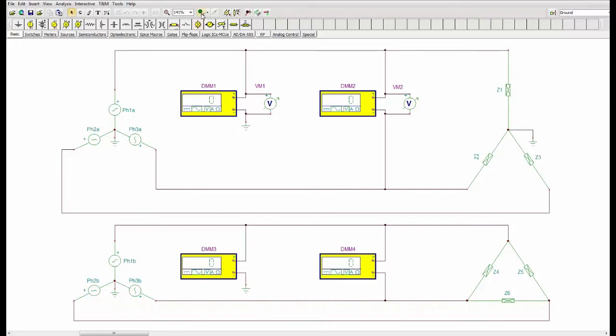Okay, so let me click on the AC simulation, and immediately we have 230 volts, and don't forget this is going from ground, or you can use neutral if you want to stick with neutral and change it to ground, that point there, from there to there. So we're looking at the voltage across this particular phase generator here. It's giving us, digital meter at least, 230 volts, so we infer from that the digital meter actually gives us, at the moment, RMS measurements.